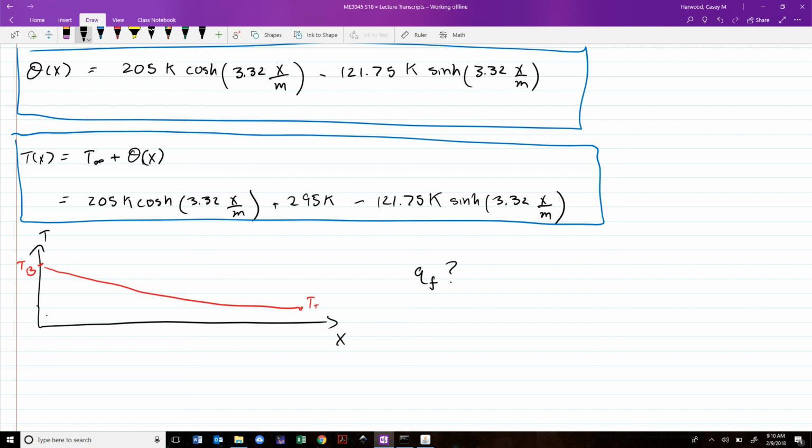All right, any heat that's leaving the fin, all the net heat dissipation from the fin, has to come in where? At the base, where it's connected to the wall. That's where all the thermal energy is entering. And by what mechanism is it entering the fin? Conduction. We have the rate equation for conduction in the form of Fourier's law.